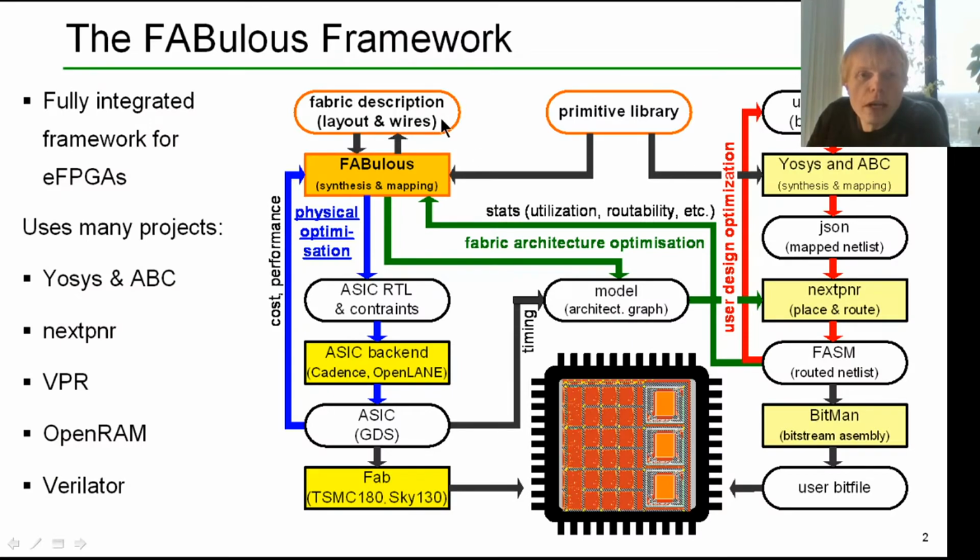It's a fully integrated framework to generate FPGA fabrics all the way down to the ASIC, as well as parameterizing the toolchain that you need to compile your own circuits into bitstreams that then will run on that FPGA fabric. There are more ingredients not shown in the figure for emulation, simulation and other things.